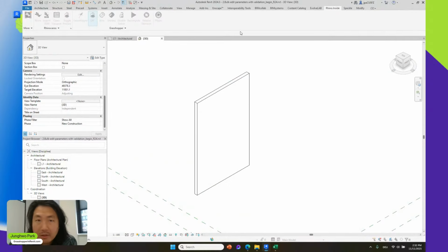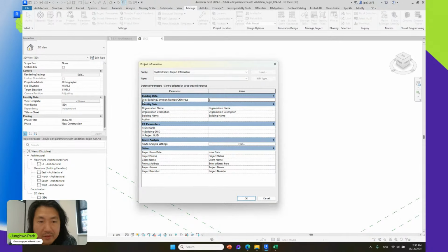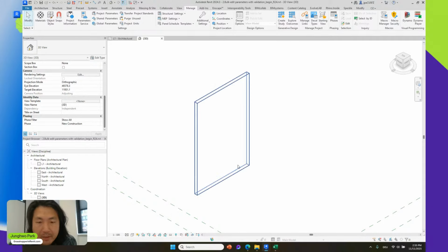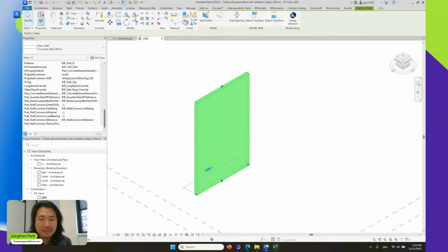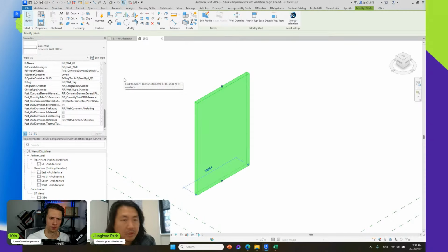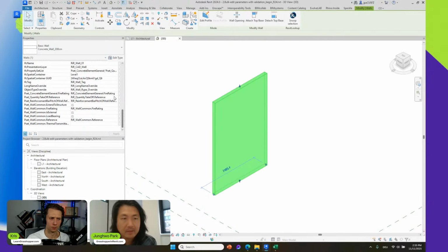So eventually in here, when you look at the Revit project information, you can see P set, property set, building common number of stories as a 3 value we are providing. So at the end, all this structural data you can export as an IFC, and then you can verify in Solibri or other IFC viewer, just to assure the quality of your model in terms of level of information. Yeah, that's all for the second example.